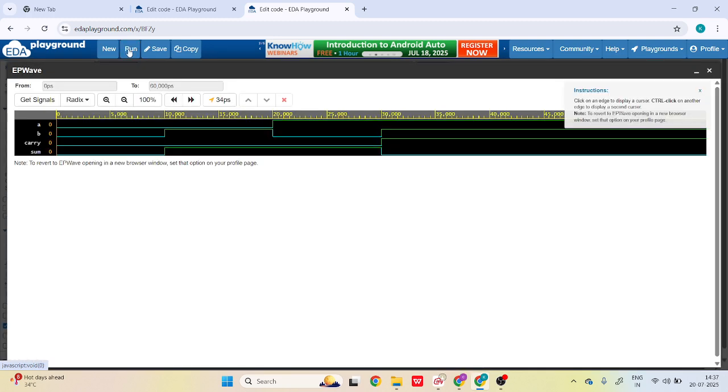Yeah, the simulation has finished. See here you can understand, actually at 0 nanoseconds, this complete simulation finished after 60 nanoseconds. Here is 60,000 picoseconds, which means 60 nanoseconds. If you want to change the nano to pico, you can.